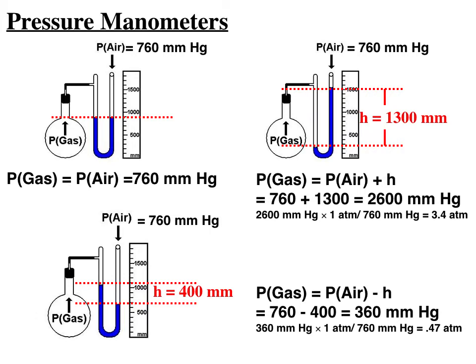And what this is implying again is what a seesaw would do. If you have a heavy person on one end, that side of the seesaw goes down. So this is an indication that the gas in the chamber is pushing harder than air, and we can even quantify how much harder than air it is pushing, provided that the liquid is mercury. Well, actually, provided that it's anything, but we have a nice connection between atmospheric pressure and mercury manometer inch or millimeter pressure. So I measure the difference in height of the left arm and right arm of the manometer, and I get a 1,300 millimeter difference in height between the two arms.